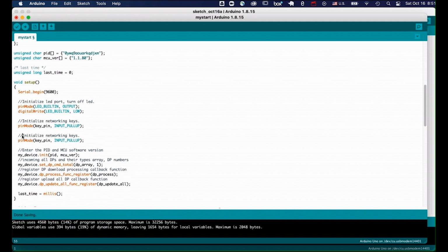What we're going to do is initialize the state of our relay. So I'm going to say right here that my relay pin is going to be an output. We don't want any pull-ups or pull-downs. Also, in case you're wondering what I'm doing, we talked more about digital inputs and outputs in previous embedded systems videos, so check those out if this is at all confusing.